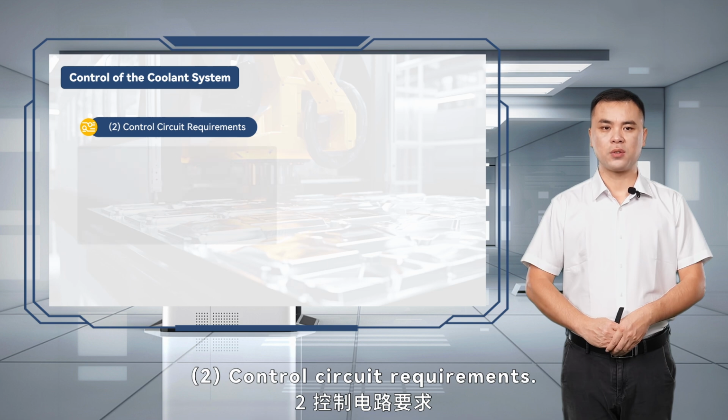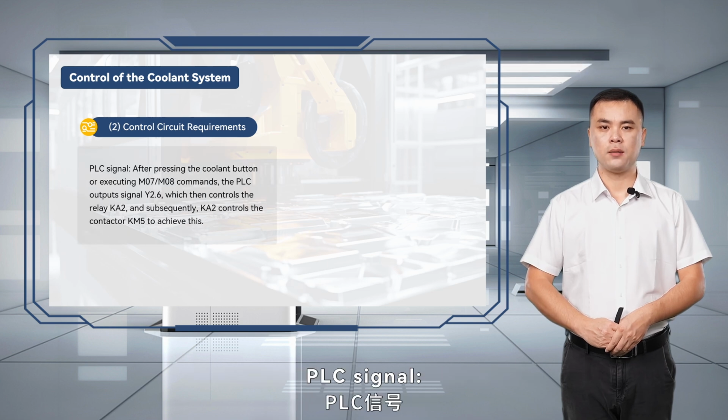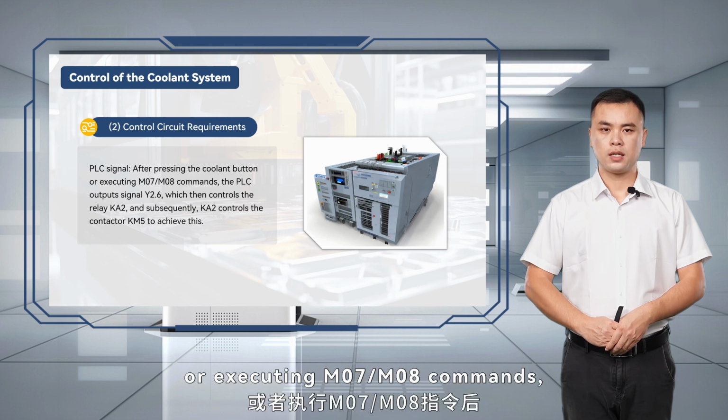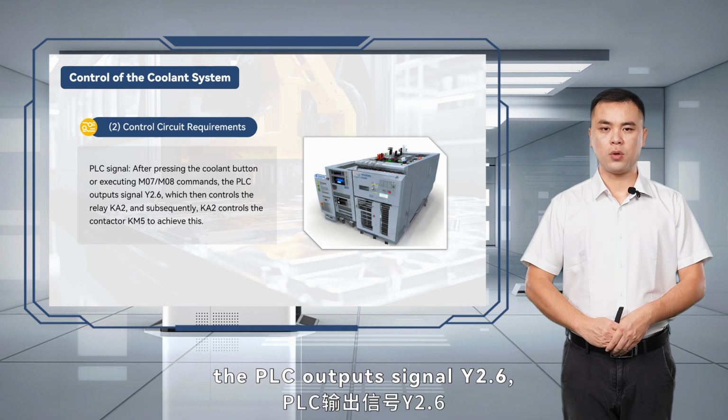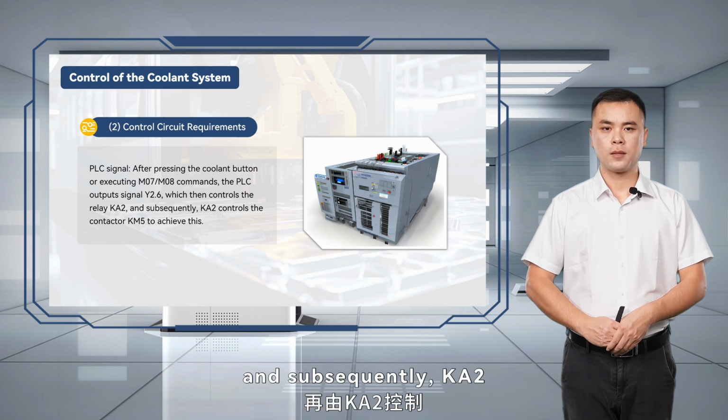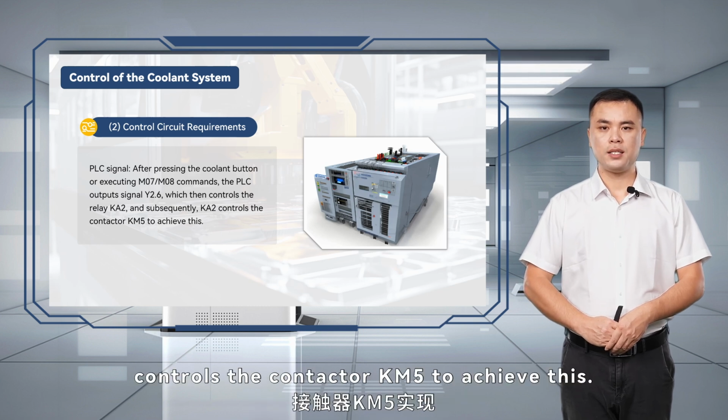2. Control circuit requirements. PLC signal. After pressing the coolant button or executing M07, M08 commands, the PLC outputs signal Y2.6, which then controls the relay KA2, and subsequently, KA2 controls the contactor KM5 to achieve this.